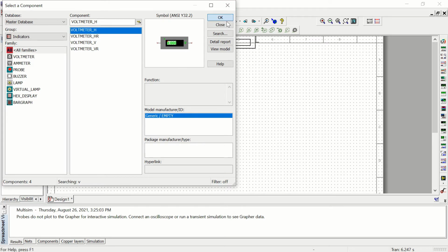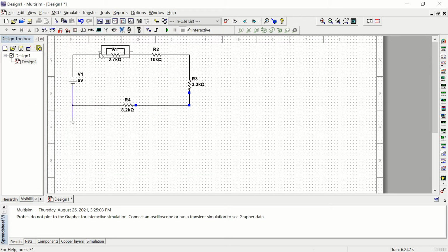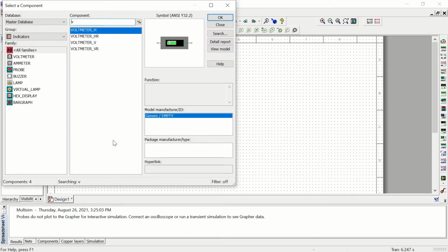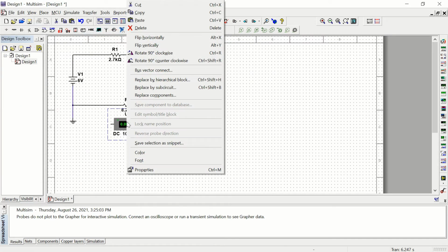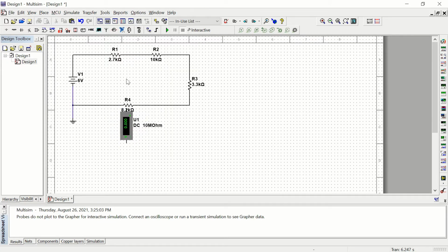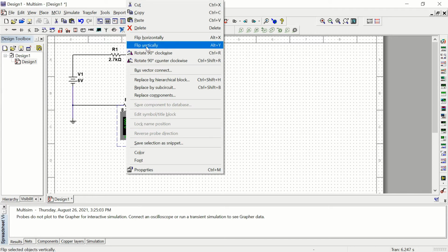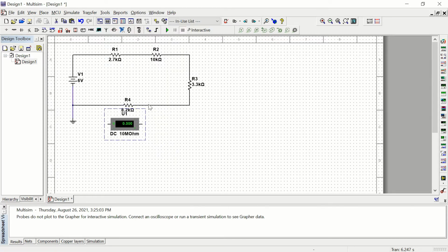So when you're measuring voltage, we'll click OK. And now I didn't really leave enough space at the top of my circuit to put a voltmeter. This is not very good. So I'll put it down here. Okay. And I think I want to rotate it. The reason I did that was because the conventional direction of current flow is coming, like this is my positive and it's coming around to my negative. And now I'm just going to hook this up.